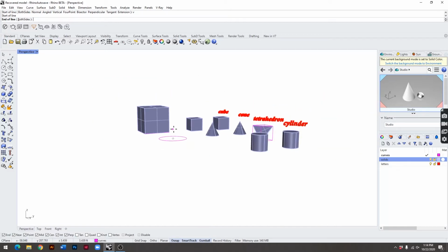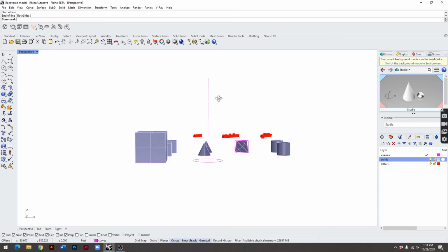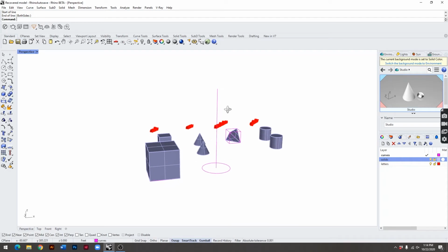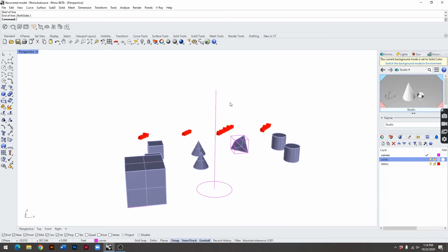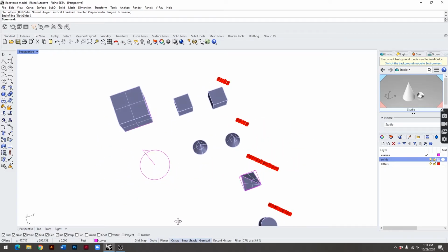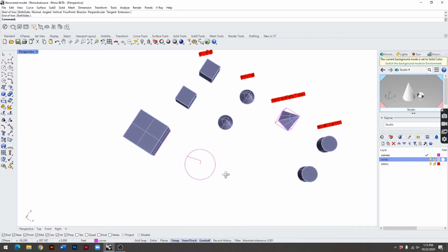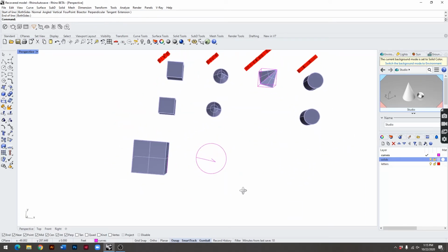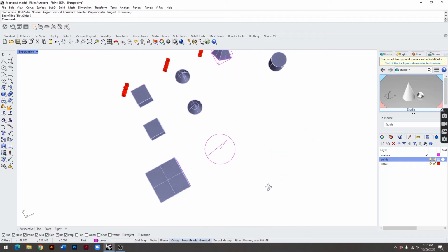Lifting up, let's make a huge cone, really tall, like a Christmas tree or something. Then we will connect the top point of this cone to any point along this edge. I like to have it at the midpoint of that circle, or the starting point, so that it fits in the orthographic view and is a little bit cleaner.